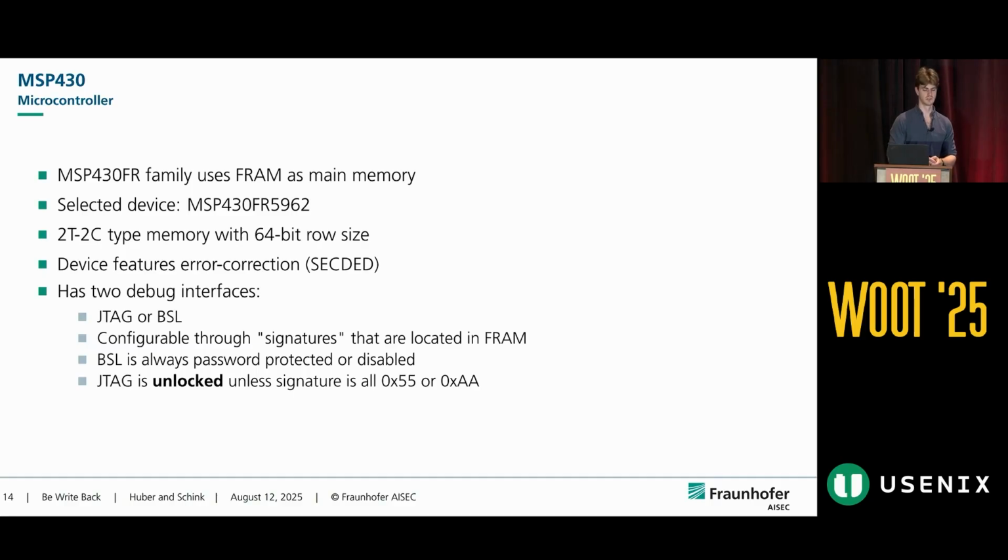Now, the bootloader is always password protected or disabled, so it's not too interesting for us. However, the JTAG is in an unlocked state unless the signature is all 0x55 or 0x88. And you can probably see where this is going.